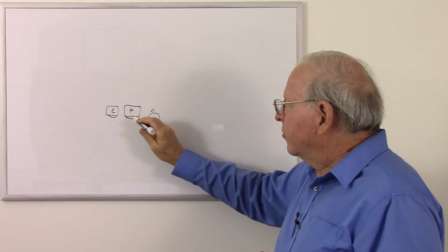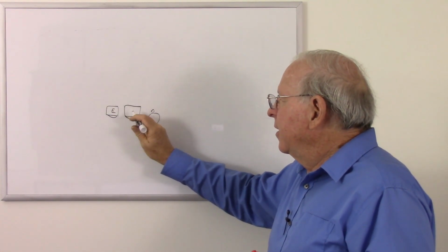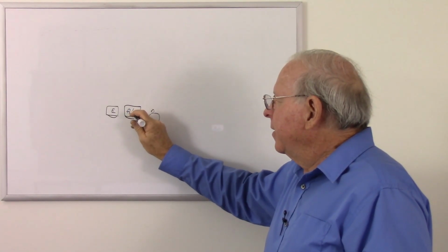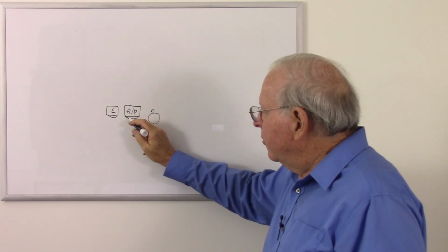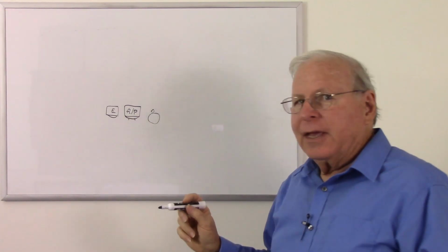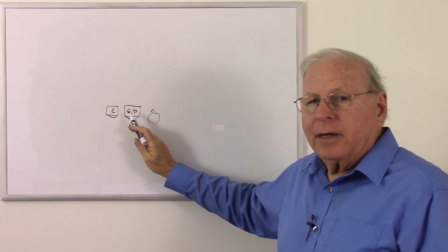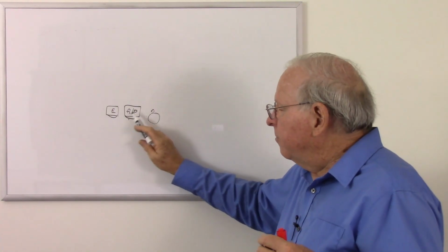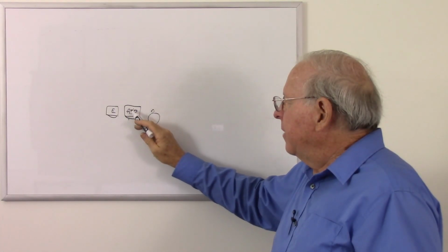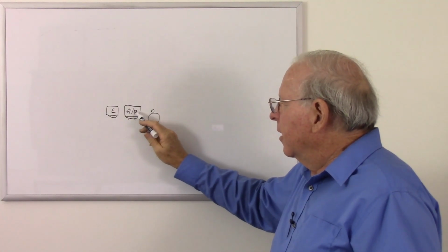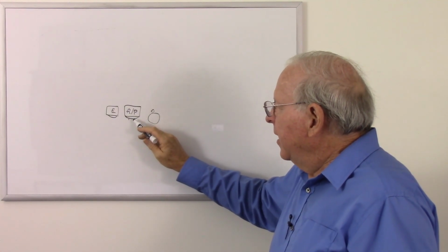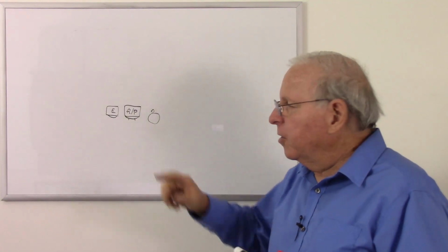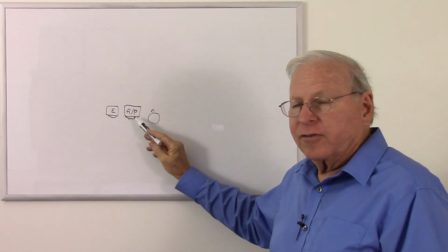Some high-end systems had a combination record playback head that actually had two separate gaps. So they had a record gap optimized for recording, a playback gap optimized for playback. So they're basically two heads in one, a complete magnetic ring with gap for record, a complete magnetic ring with gap for playback. And of course you could do the same thing here as with the reel-to-reel. You could monitor while you were recording. So this would be for high-end cassette recorders.